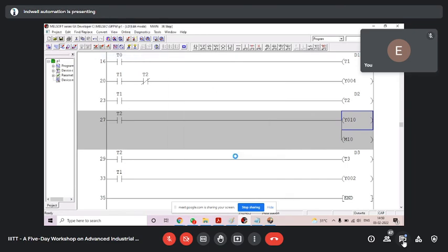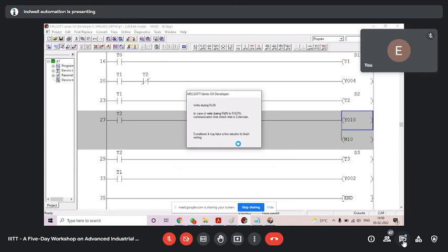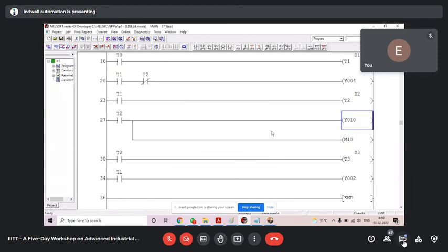So done, you see, it is done. So if I convert, I will have to send the complete program to PLC, and in that way, PLC will stop, your machine will stop. But if you do a small modification and you do convert online change, that is online edit actually. In run mode, in running process, modification can be done.